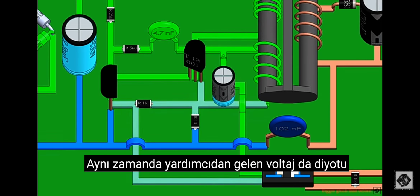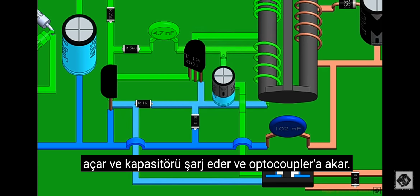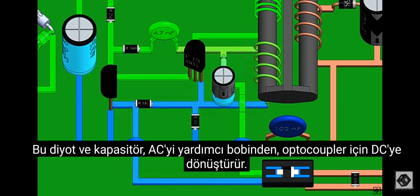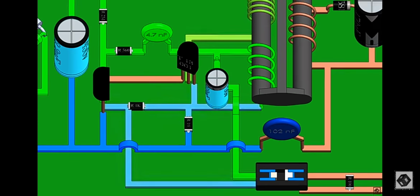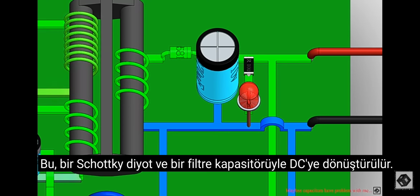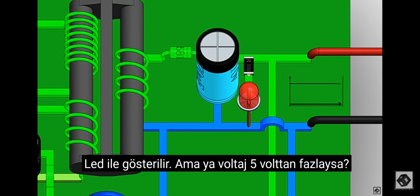At the same time, the voltage from the auxiliary also turns the diode on and charges the capacitor and flows to the optocoupler. This diode and capacitor convert the AC from the auxiliary coil to DC for the optocoupler. The current is also induced in the secondary winding. This is converted to DC by a Schottky diode and a filter capacitor. It is indicated by the LED.